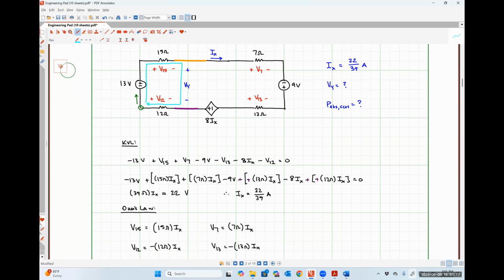It literally doesn't matter a lick that there is no current flowing down between that orange node and that purple node across that open circuit. Doesn't matter at all, because Kirchhoff's voltage law just says that the sum of the voltage drops around any closed path has to be equal to 0. And we know that voltage is just the difference in potential between 2 points. So it doesn't matter if those points are connected to each other or not.